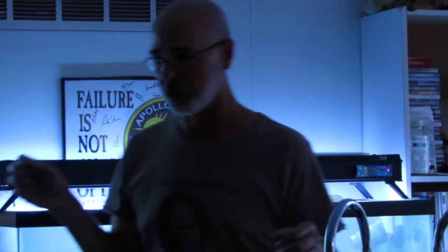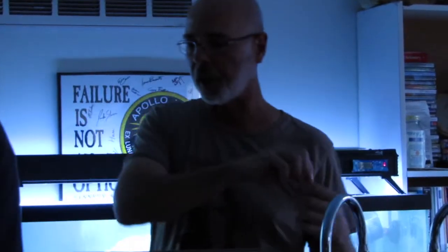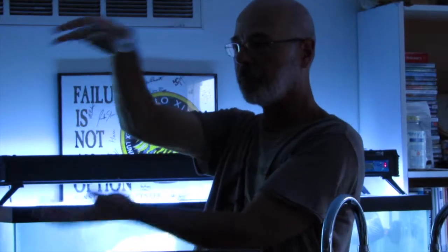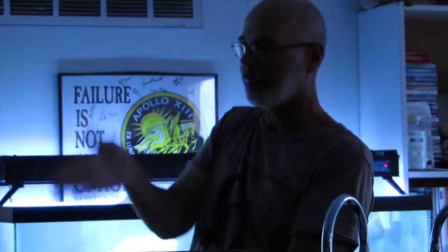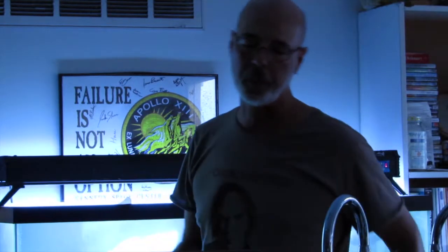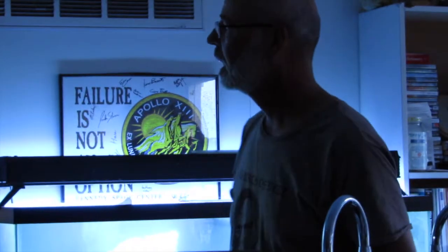Analog scopes, the way they work, I really love analog scopes because they are very intimate with the circuitry. Whatever you see in the circuit is exactly what's displayed on the screen. The voltage comes in and goes through to a couple of plates above and below the CRT screen, and it charges the plates in varying amounts, and that makes the electron beam go up and down. And then there's plates on the side which the horizontal sweep uses too. So what comes in goes right to the screen. It's immediate. What you see on the screen is exactly what's happening in real time.